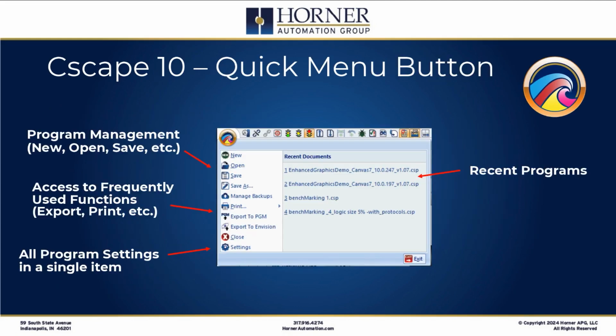Okay, so let's start with the user interface changes, how Cscape 10 looks a little different than Cscape 9 and earlier versions. And we'll start with the quick menu button. So the quick menu button is up in the upper left-hand corner. It's a button that you press with your mouse, and it effectively gives you the most commonly needed program management functions for your application. So, I need to create a new project.